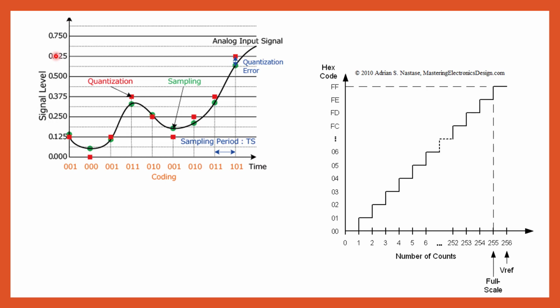Well, it depends. Sometimes things are changing so slowly that we don't have to capture it. Or they're changing so slightly from one value to the other that we don't need to worry about that either. If I'm wanting to, say, convert the temperature in my room, in my office here, to digital, it's an analog process that's going on. My temperature in my room is rising and falling a little bit. The heater kicks on, it goes up a little bit, then it cools. If I want to capture those changes and convert it to digital, then I need to take those samples.